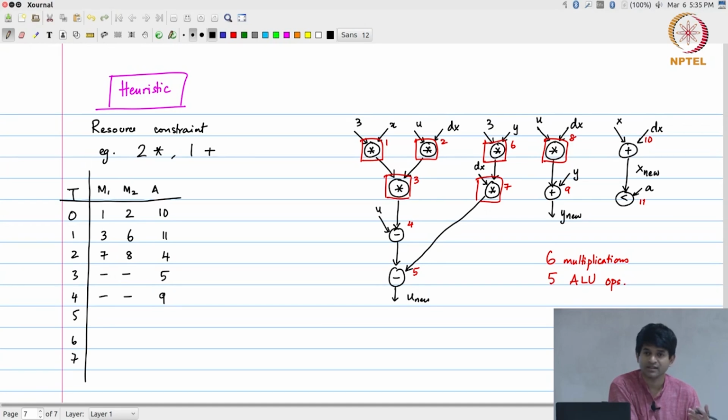Could I have reduced that and made it 1 multiplier? What would have happened then? I would have had to push to 6 clock cycles. Okay. So this already shows you an interesting sort of trade off over there, right. If I reduce the multipliers from 2 to 1, right, automatically it would have pushed it to 6 clock cycles, but then possibly I might have got a schedule where the multipliers could be running at 100% utilization.